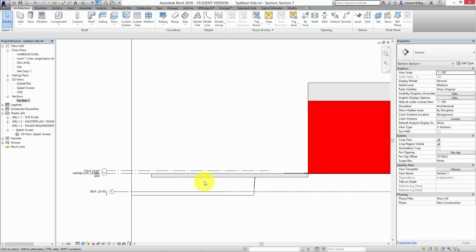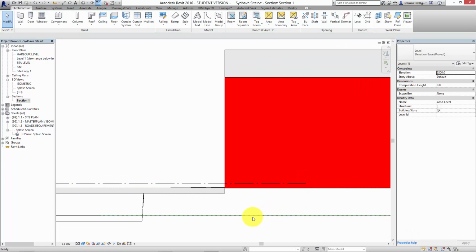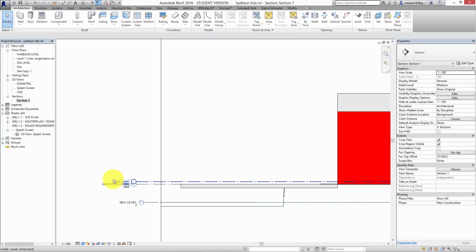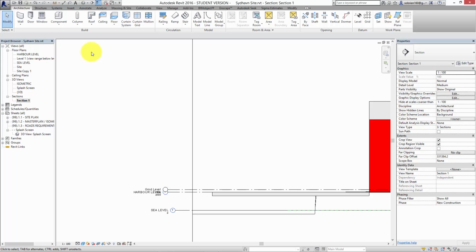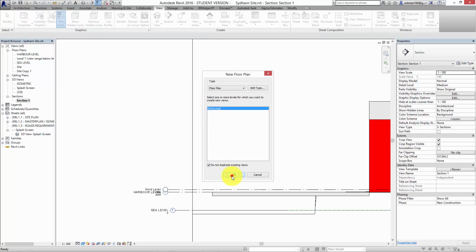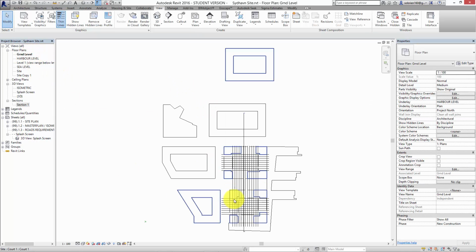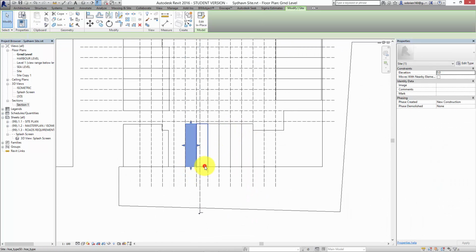And let's say that takes care of all the modeling regarding the external areas and so on. So now we have a level to put the house on, ground level. So let's go to view, plan views, floor plan, and we'll make a drawing for that level. So now we have a ground level view, which looks something like that at the moment. Here we have these massing elements down the front, 6 of them, which are just placeholders for the house.